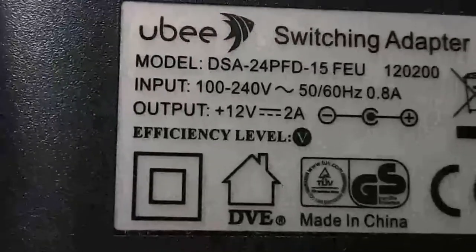Let me see if there's something else. This thing also has the same barrel jack, so that's fine. And it runs at 12 volts, 2 amps. So that's the maximum it can deliver. It doesn't mean it delivers 2 amps, because that depends on the internal resistance of what you connect it to. But it can deliver up to 2 amps. We only require 1.2 amps, so this one is pretty good. Even if it could deliver 10 amps, it won't deliver 10 amps. It depends on the resistance of the device you connect it to. So that's it, 12 volts 2 amps. This would be a suitable device. It's not at its max capacity, so it will run better.